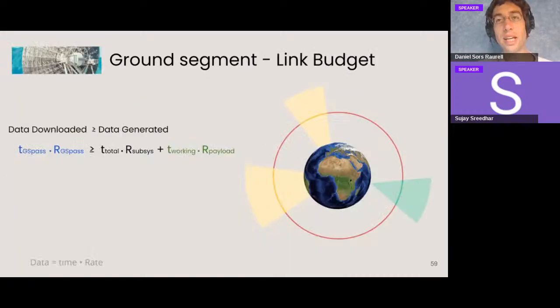Now I'm going to mention the link budget. You will see in VApp some of the graphs regarding the link budget, so you can see the memory, all the data that you are storing, and all the data that you are downlinking. If you zoom in on some of the graphs and make them big, you will see the link budgets there. That's calculated straightforward. That's very important to take into consideration during mission design, especially when designing your mission in phases 0 and A.